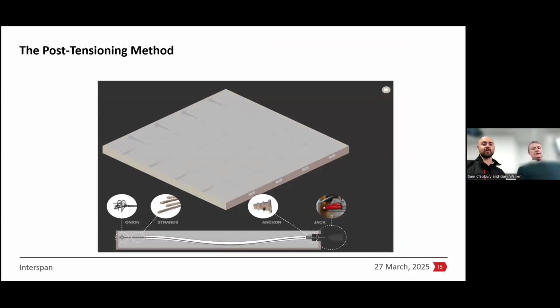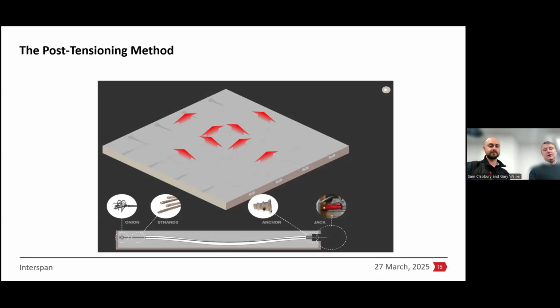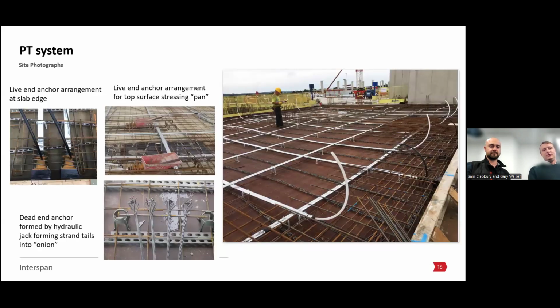There's a little animation off our website just to show you the post-tensioning in action when we do the stressing, so you can get an appreciation for the equipment being used. A hydraulic jack comes and stresses the tendons, and as they lift the drape up, we're counteracting. There's a load balancing of the self weight of the concrete that occurs when you stress the slab. So that's how we can control deflections better than an RC slab, because we're actively balancing that portion of the self weight. The portion can be up to 80-90%.